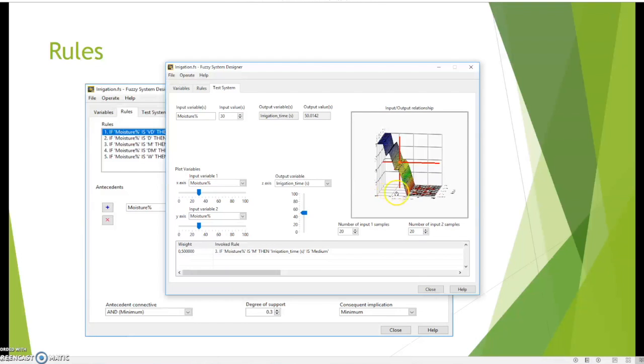This means that this is basically our control interval. When I change the input values here, we can see that the output value is following the characteristic output function, and we don't get really abrupt changes in the output value. Here we see how the output values are changing pretty smoothly following the output characterization function.